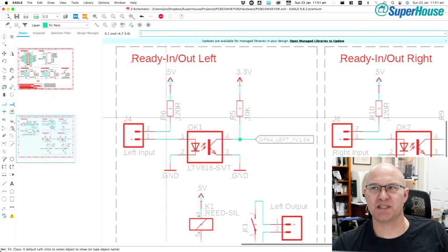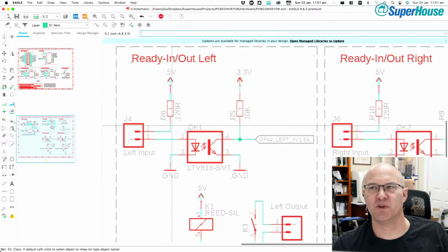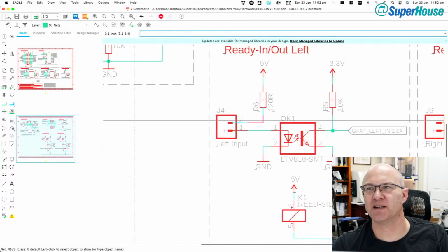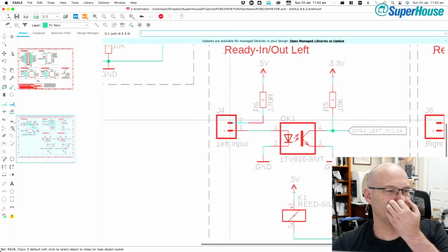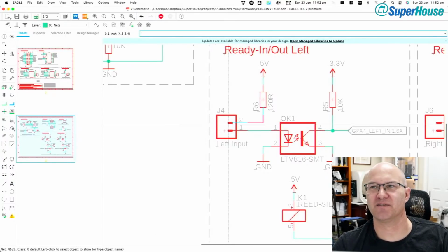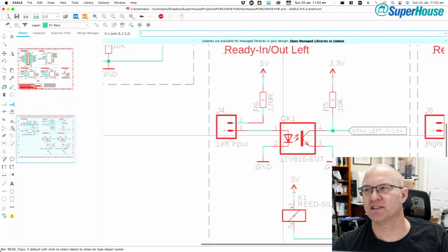But this is potentially a danger, because what we are doing here is taking the 5 volt rail and exposing it through this resistor out on this wire that could potentially run meters and meters around a factory, past big electric motors and arcing plasma cutters and all of that sort of horrible stuff, and then coming back around and into this side of the optocoupler.